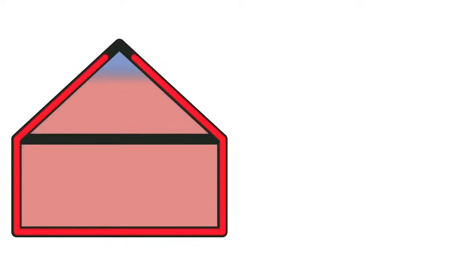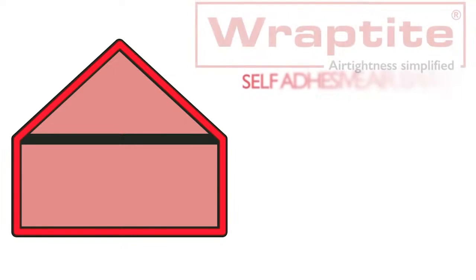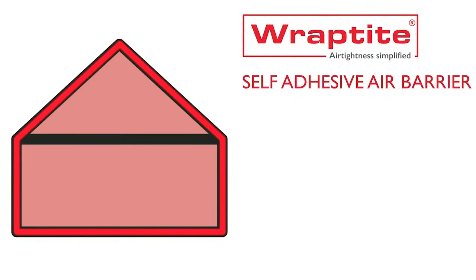In terms of today's discussion though, the simplified answer is to consider that for very airtight buildings, a warm pitched roof with an external air barrier layer presents a far more optimal solution. This is particularly true where this air barrier solution is also applied to the wall constructions. Using a continuous layer of our Wraptite external air barrier around the entire structure will facilitate the passage of moisture, whilst providing an effective air barrier.